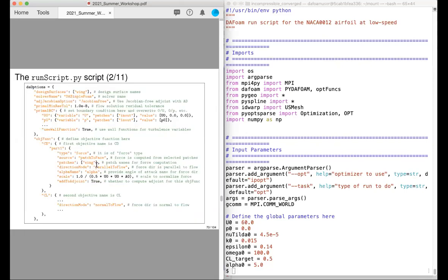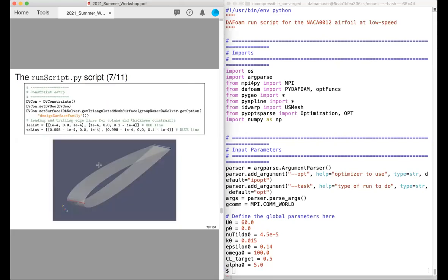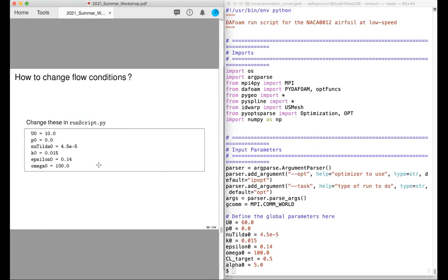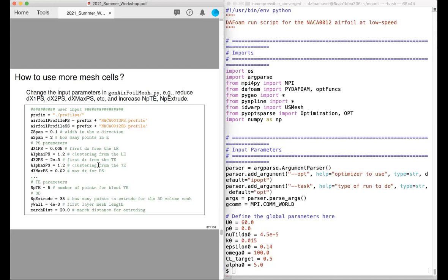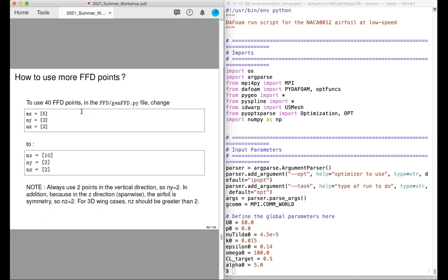Here we go. Oh, I guess I missed it, it should be somewhere in these slides, and I can't find it. But if you check the slides, there is a script that you can use to convert plot3d into Tecplot format and then load it in ParaView. Okay, don't directly load the plot3d format because your ParaView will crash. Okay, that's how you increase the FFD points.